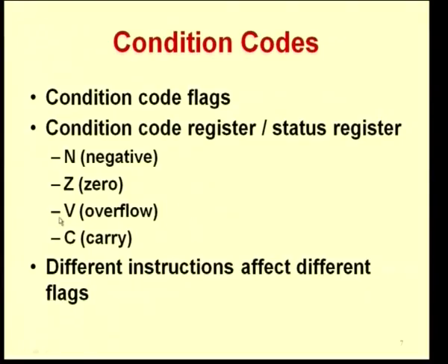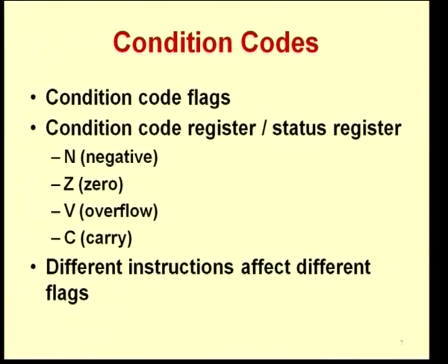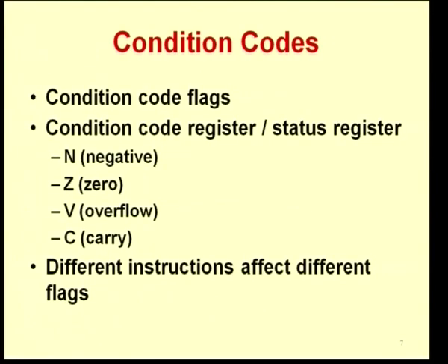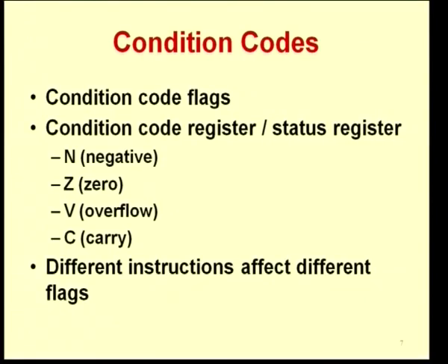Then you have an overflow flag, a V flag. This means that the previous operation ended in an overflow condition. You have overflow conditions when you are adding, let us say, two numbers and the result is not able to fit into the register. You have a value which is greater than what can fit into a register, so you have an overflow condition. The other is a carry. We all know what a carry is. In case a previous operation, say an addition, generated a carry, then the carry flag is set. So these are typical flags that are set.